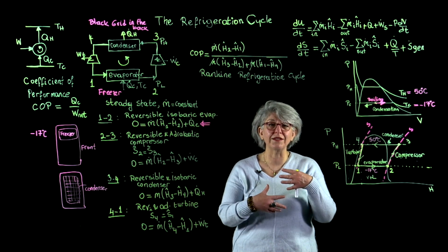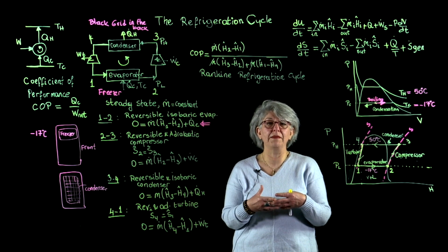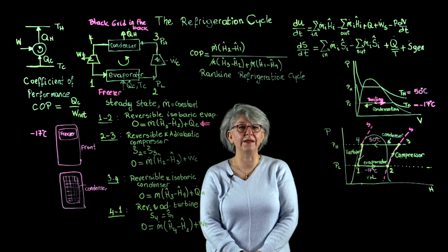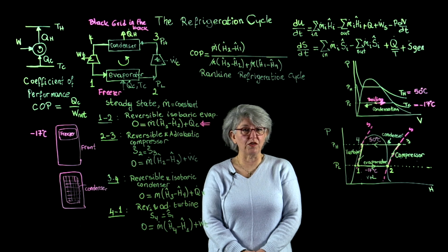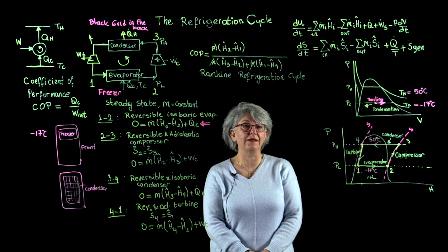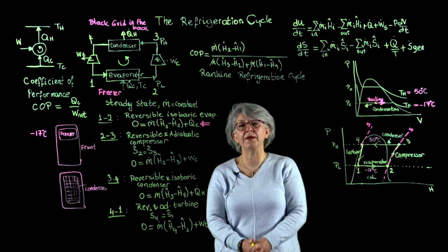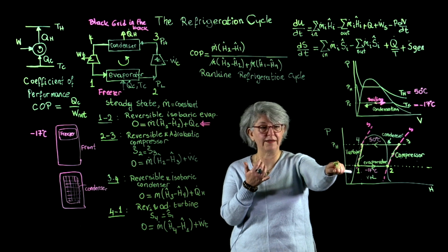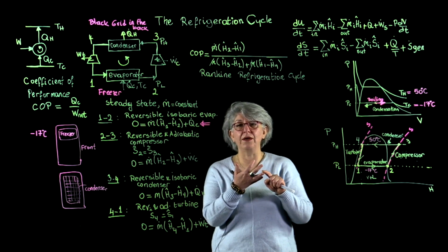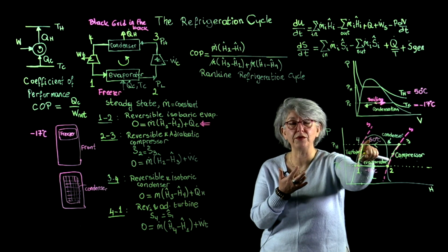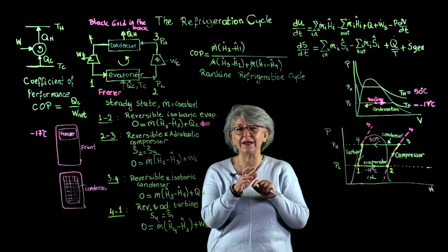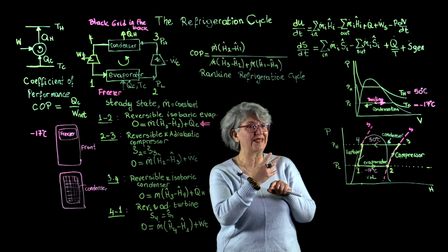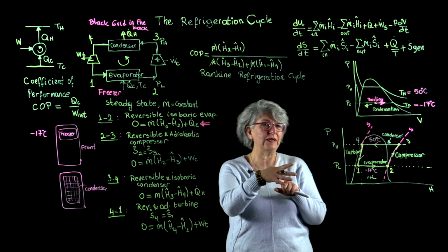So there was alternative material that was being sought, and that alternative material had to fulfill the following requirements. It should have boiling point at that temperature, at atmospheric pressure, boiling point at this temperature at around, say, 5 atmospheres, 10 atmospheres, not more than that, right?